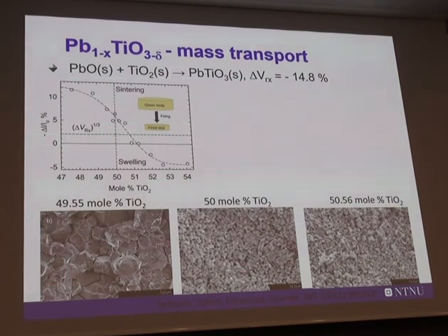Do you have any examples where there is an absorption of water in ferroelectric materials and the losses have been higher or lower or something? There are examples where people have claimed that there is water involved, but there is not really. In most of the ferroelectric materials, the water absorption concentration is fairly low. It's very hard to characterize that it is water and has the properties of protons.